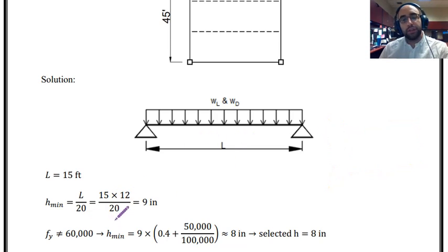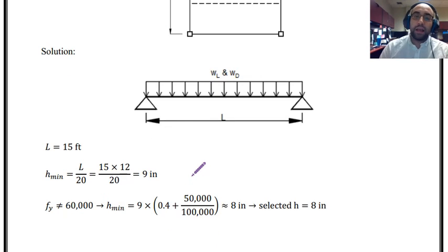You can see the height is equal to 9 inches. So I'm going to take that as the height, and I'm not going to change it because for the slab we do not have a great amount of load. Specifically in this case it just said self weight, so I know just by considering this section size I will have enough strength. Of course this is based on experience.